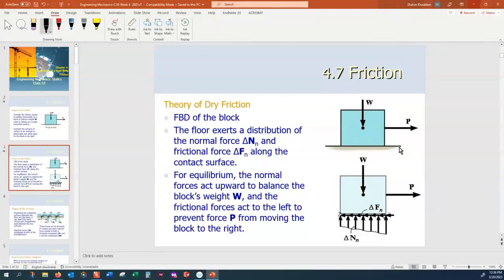And that is understandable because why this friction develops, there are asperities, there are rough surfaces, something like the hills, like the sharp edges, they entangle mechanically together. And as a result, the motion becomes difficult. So you only can move when you manage to break those tiny asperities. And once they break, they don't disappear.